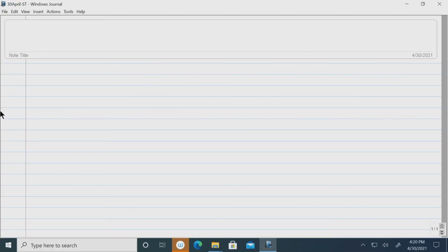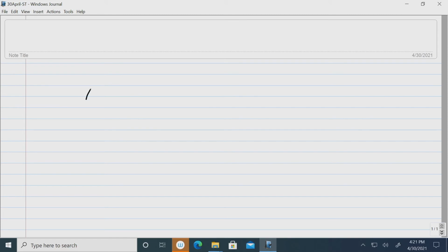So, we have the thickness of the shell as 75 mm and you can see that span of the shell is mentioned as 12 meter. So, in relation to span the thickness is very small. So, it is a thin shell. So, let us find out the design quantity. We have this shell, it is a spherical shell of very small thickness, but covering a large area. And it is supported over an edge beam.